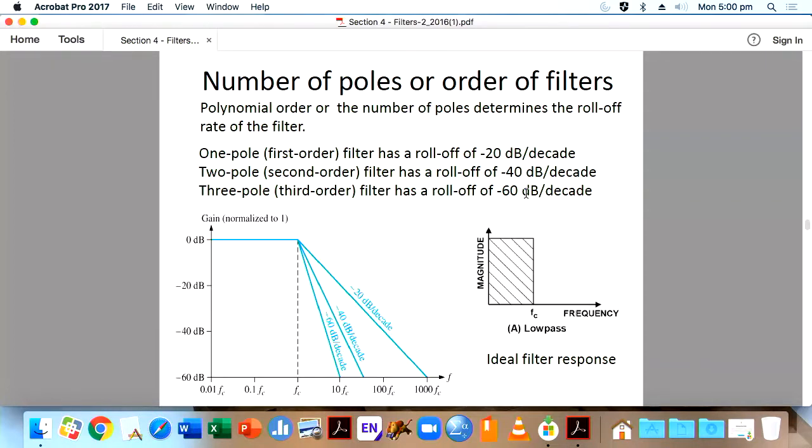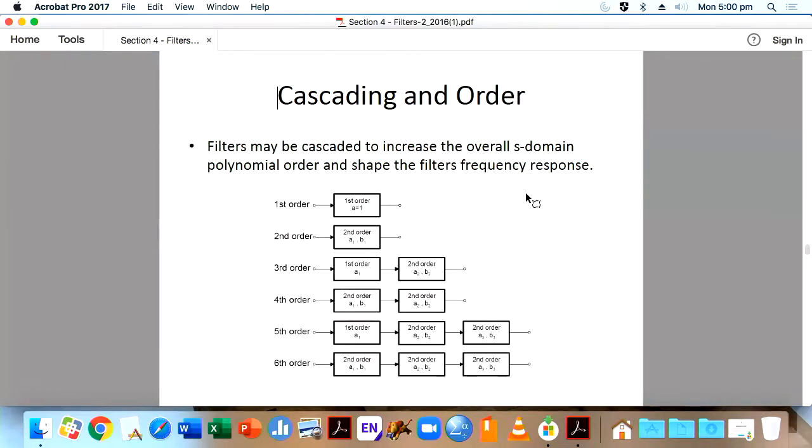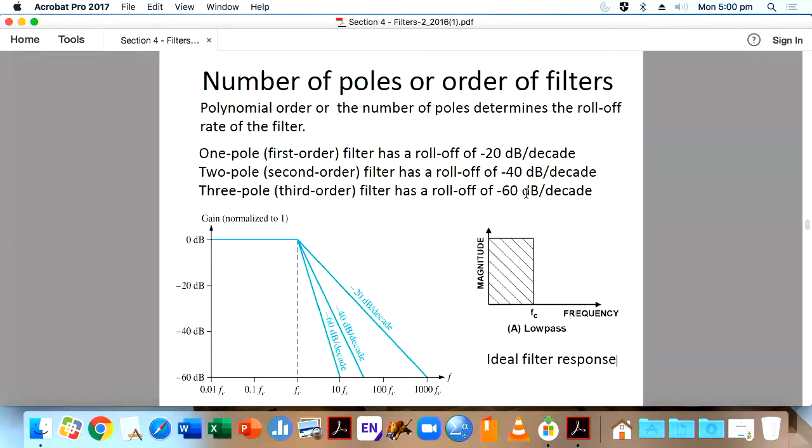So you have to make a decision, plus what extra thing you are going to design. Maybe you got some space, then maybe you can design a fourth order filter and use some space, or you want to leave that space for your innovation. You know what I meant? So you have to make a decision. Having said that, many students in the last year used 2 poles. Only some used higher poles. So second order might be enough for you, but it's again up to you.